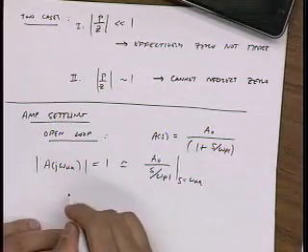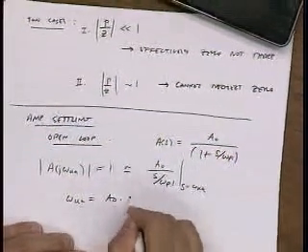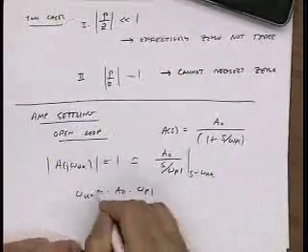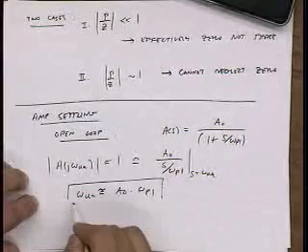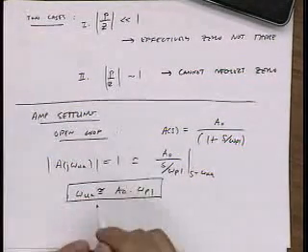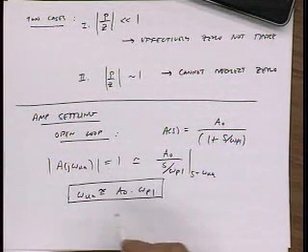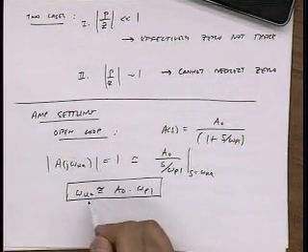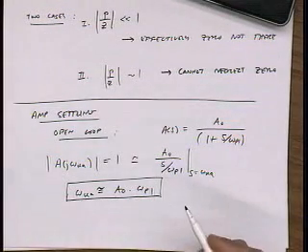And so then I can solve for omega UA is A naught times omega P1, roughly. Okay. So pretty simple, right? I have an amplifier, it has a dominant pole, and roughly then its unity gain frequency is the pole times its DC value of gain.